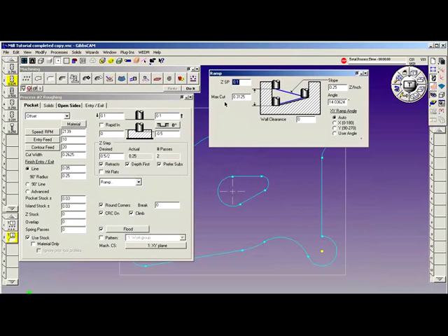Z start point, maximum cut defaults to the radius of the cutter. The slope determines the entry angle. Slope and angle are tied together. 0.5, increase the angle. 0.1, decrease the angle. The XY ramp angle, we can enter the work along the X-axis, the Y-axis, a user-defined angle, or the default auto, where the system will determine the optimum entry point and get into the work.